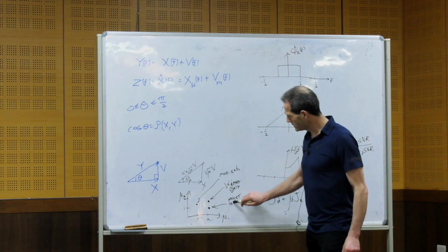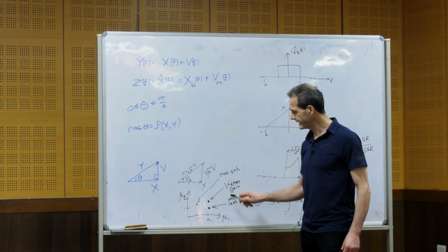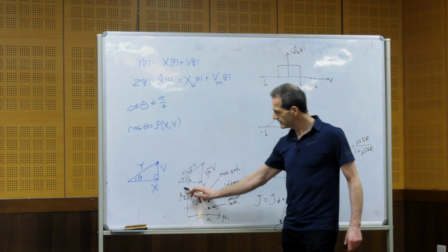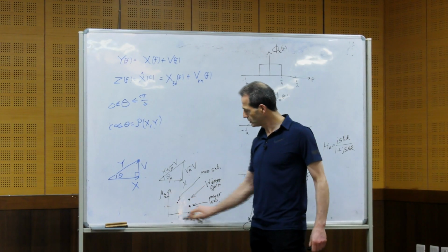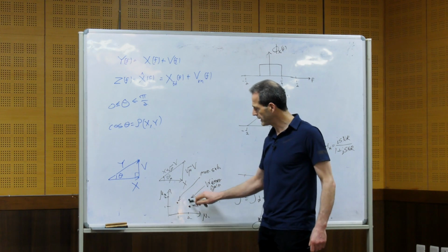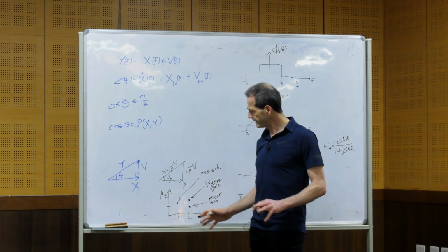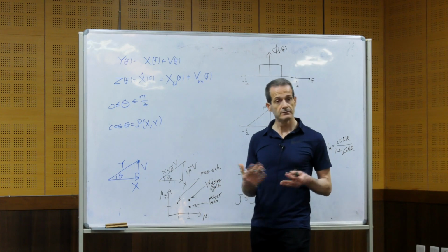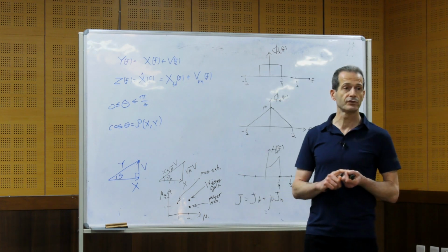So the power subtraction method, the magnitude subtraction method and the Wiener gain are all known in the literature. And we see that they are special cases of the parametric gain that can be obtained with other values of mu1 and mu2. And then we can ask ourselves, okay, we know about these three, but what happens if I choose different values and modify these parameters? That is also a nice method to obtain different trade-offs.